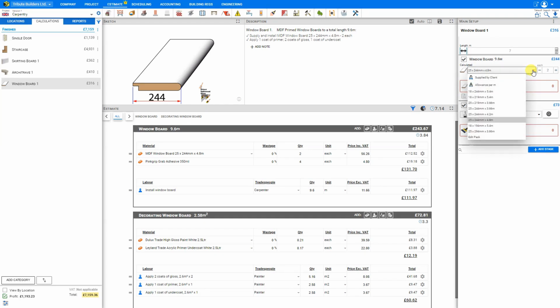But if we were to choose a shorter length, let's say 4.2, that would reduce our costs, but still give us excess length. So let's see what happens if we reduce that further. Maybe we can find a more cost-effective amount. And there we have 2 3.6 meter boards. That's still sufficient to cover our required length, but the remnant for these will not be sufficient to create one single board for our 7th board.